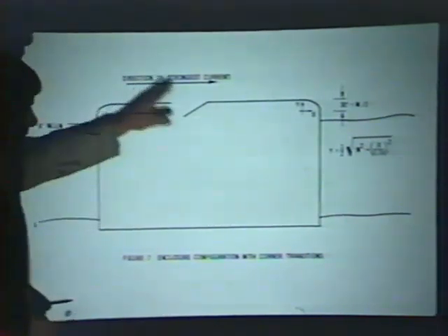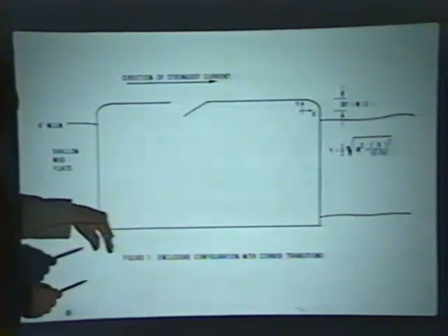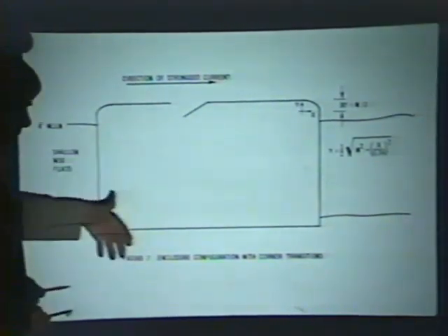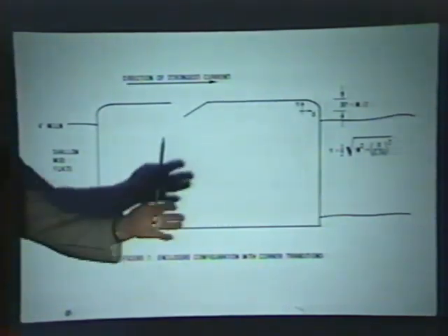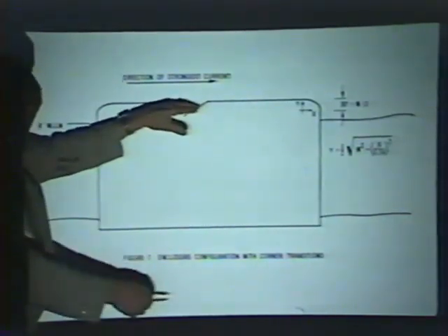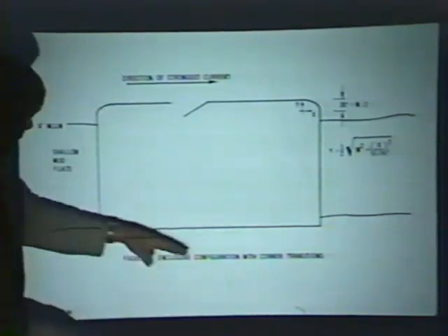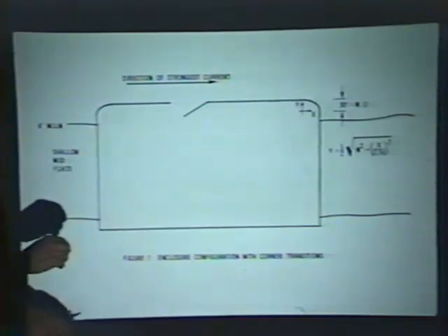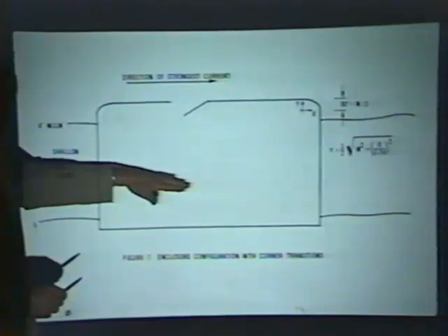That's normally not a problem unless the harbor has a part that's a long way from the entrance, where the residence time is very long. But if you do, then you have to have some kind of a pump. It's important that you be able to block it off, however, so that you don't have circulation during periods of high suspended solids concentration. Usually there's an algae bloom in the summer when there's low flows, and you need the circulation then, and the suspended solids concentration is low, so it's not a problem. But you want to be able to close it off during periods of high suspended solids concentration.